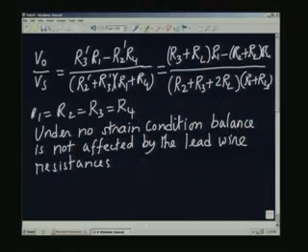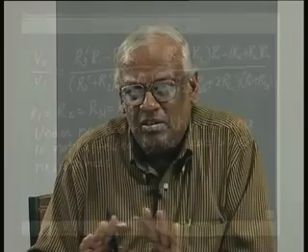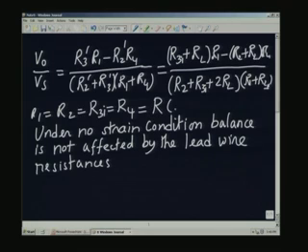Now, let us see what happens when the balance is not there and the resistance R 3 has changed by a small amount. So, in fact, if you would like to look at it, I can make it R 3 I here, to be consistent with our earlier notation. Now, what I am going to do is I am going to perturb this R 3 by a small amount, and remember that R 3 I is equal to R 1 equal to R 2. So, here also I can make that equal to R 4 equal to 120 ohms or whatever, equal to some R, let us say, whatever may be the value. So, I can in fact simplify this expression by putting all these resistance equal to R common value, and before we do that, let us just look at what happens in the unbalanced condition.